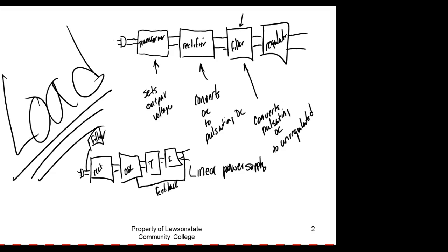be a lot bigger. This is 20 volts at 3.5 amps. So the transformer would be huge, and the filter capacitors would be huge. This would probably be maybe 5 times bigger than this if it's a linear power supply. But this is a switching power supply.